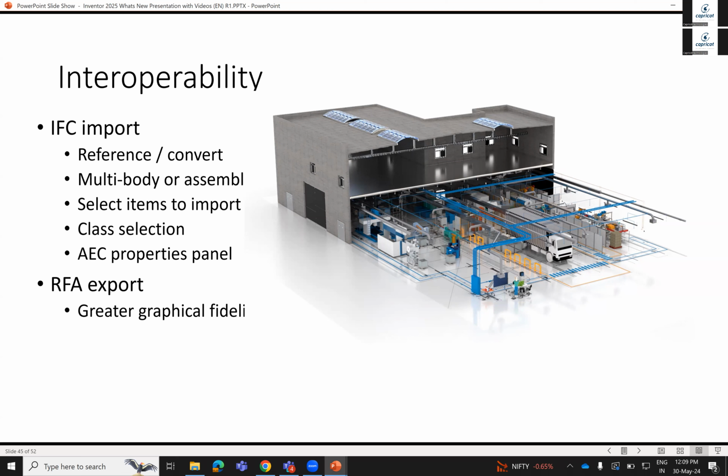Including those who use some structural projects, they do an FEA simulation and they want to bring the same data to Inventor to create the frameworks. Because what they use in the third-party CAD software, like IFC files, doesn't have all the supports and other things. They just finalize the sizes and the thickness there. And for detailed fabrication drawings, they use Inventor Pro frameworks. At that time, you can bring that data. We call this data crossing interoperability.